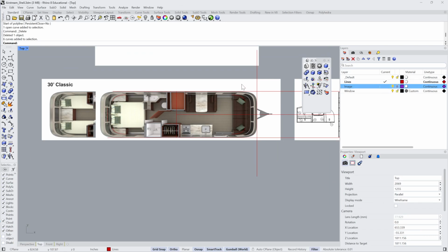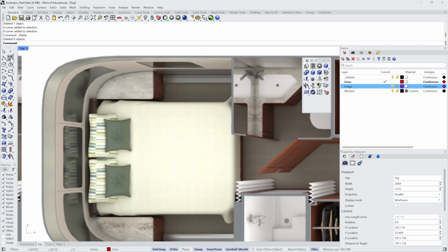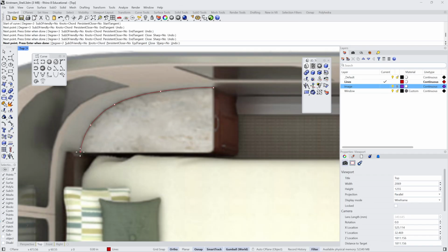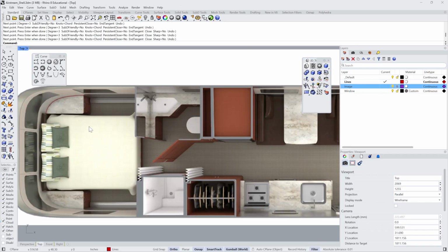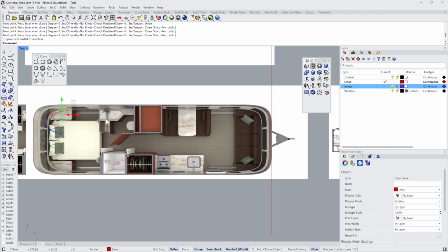Just so you understand how I did it, because I think it's important to get this kind of thing right. Let's say I'm going to come over here, and I'm going to draw an interp curve. And some sort of grid snap on, which I don't want. And then I'm holding down Shift, and I'm just tracing this curve like that. Okay. So now I wouldn't want to trace this 4 times because I know that it's the same, right? So what I really want to do is let's mirror it.